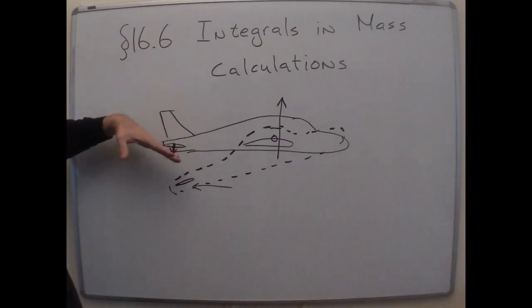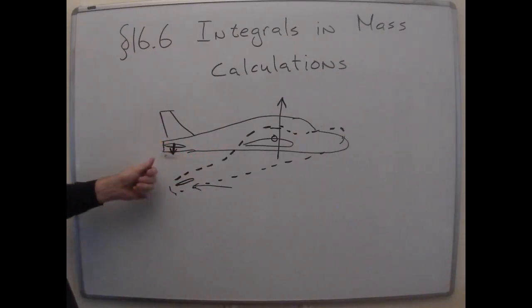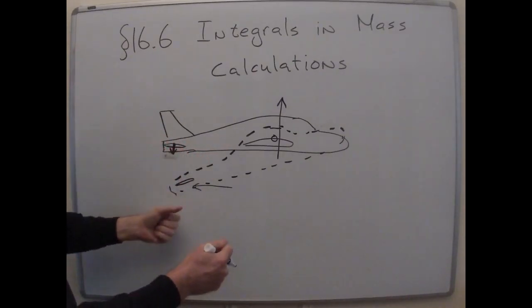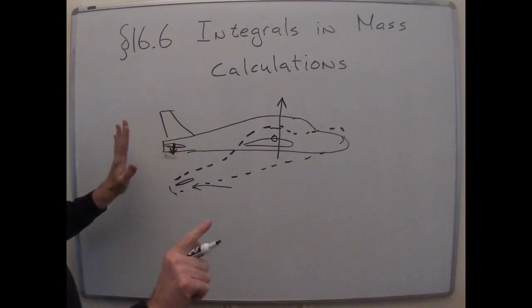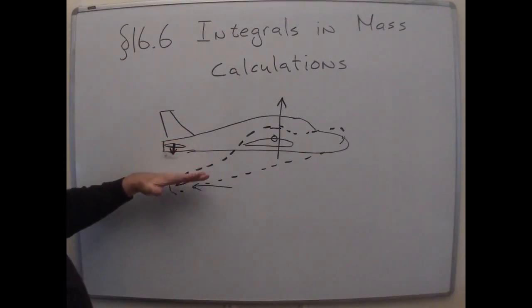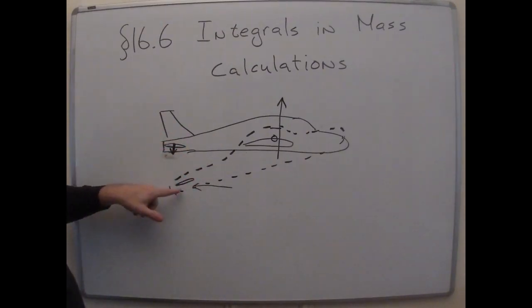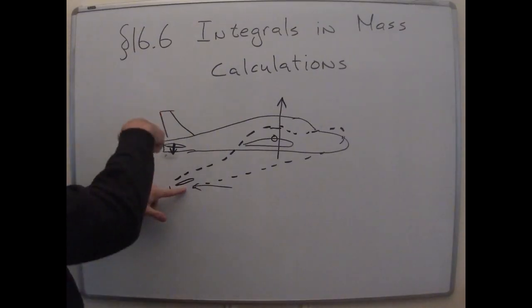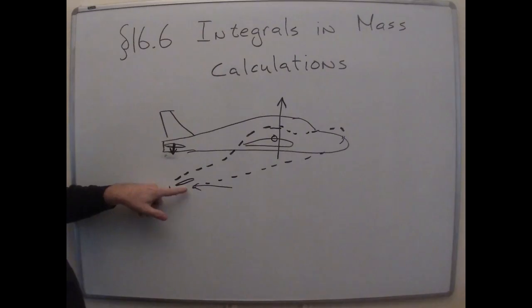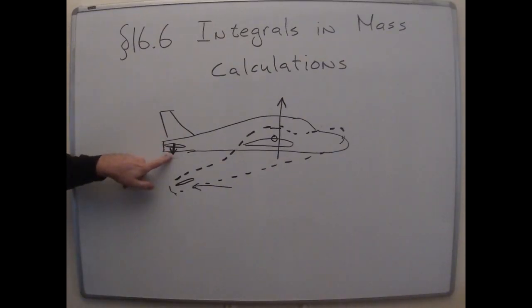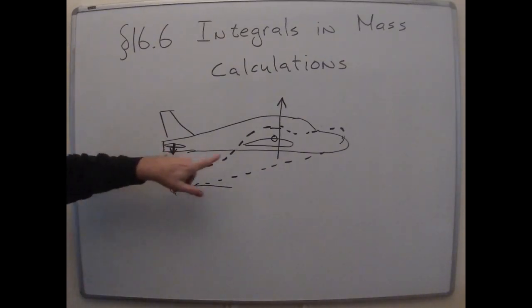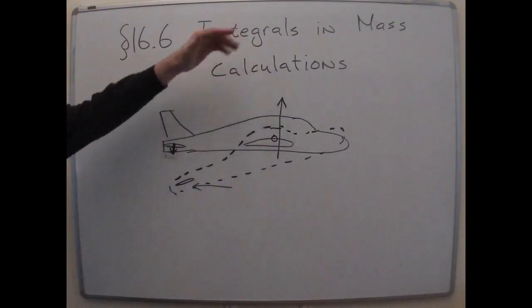Now, of course, if the pilot wants it to rotate to the upward position, he adjusts the angle of this thing. That's what pulling back on the wheel does. You change that angle slightly. But if you're not doing anything and you end up, for some reason, getting into this nose-up position, the lift on the elevator will, or rather the down force on the elevator will go away. It may even turn into a lift, and so the airplane will return to the position it was in. Right. So you want there to be a small negative force back here and a large positive force from the wings up there. That's the way you want things to be.